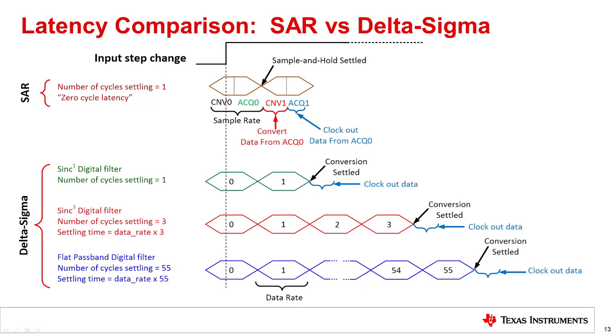It is important to remember that latency is not always a key consideration. For example, in an audio system, an ADC can be used to record sound. In this case, a short delay between when the sound is detected by the microphone and when the conversion is stored in memory is not an issue. On the other hand, in a safety system, the ADC may be monitoring a sensor where a near instantaneous response is required. In that case, latency may be critical. You will have to determine whether or not latency is important for your application.